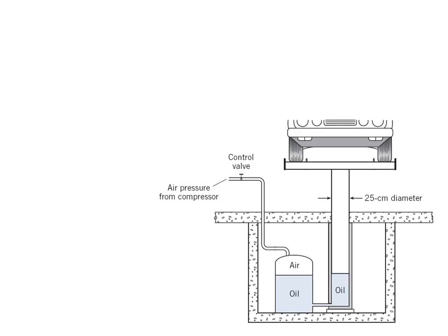It's not pictured, but at the end of this tube is a compressor. If you want to lift this car, you turn on the compressor, and what the compressor does is it pumps additional air in here that pushes down on the oil, and that downward pressure on the oil pushes up against this cylinder, and then it basically will lift the car.